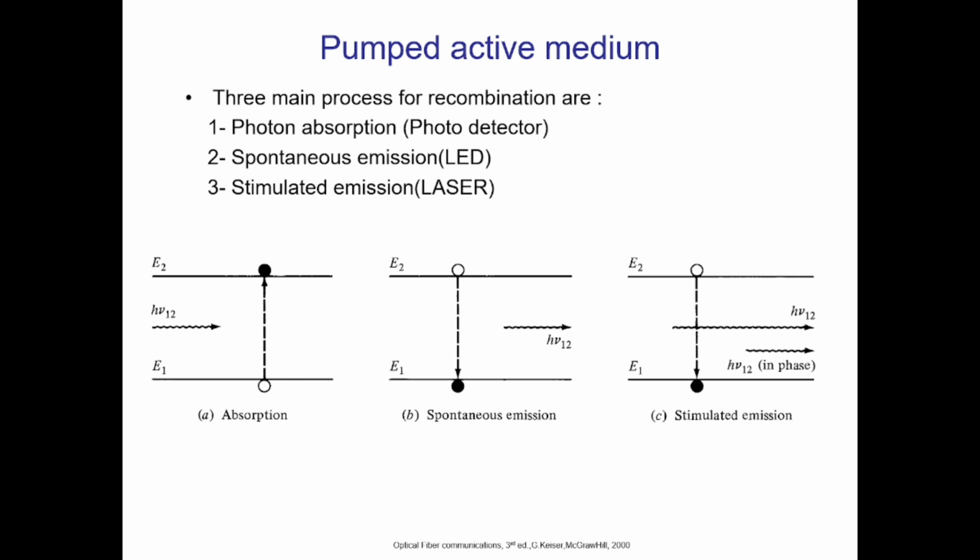In stimulated emission, even with a single electron hole carrier, you are injecting a few carriers that can lead to multiple emissions. And multiple emissions lead to in phase. The emitted photons because of these injected carriers will be in phase with what is emitted normally. That will be in phase with each other. So you will have a coherent light generation in stimulated emission. It will have in phase propagation, that is coherent. The generated light will be coherent light, but in spontaneous emission it is incoherent light.